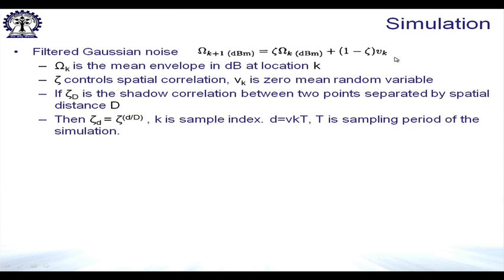Now, for our particular course, we do not need all these details of correlated shadowing and so forth. What we can at most use is the path loss exponent and shadowing. Most important to remember is that these models provide us with the average received signal strength as a function of separation distance, along with certain random fluctuations. We will be concerned with the signal attenuation only. Once you study mobile communications in a different subject, then you need even more details of shadowing to calculate the boundary coverage probability and so forth. With this, we more or less summarize large scale propagation models.